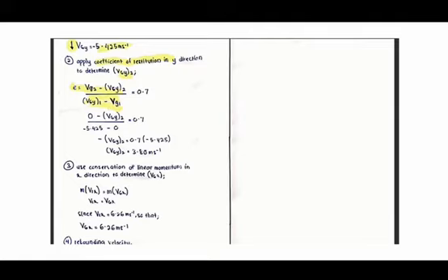So vg2 is 0 minus vgy2 which is unknown, divided by vgy1 that we found in the first step, negative 5.425, minus vg1 which is 0. E, we substitute 0.7. Then we rearrange the equation and we get negative vgy2 equal to 0.7 multiplied by negative 5.425, and the final answer we get is vgy2 equal to 3.80 meter per second.